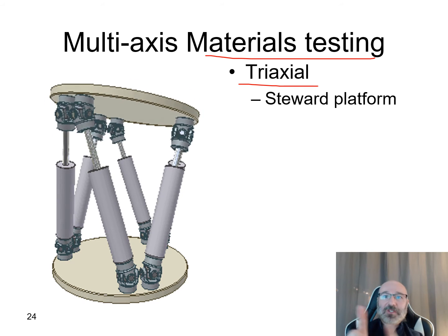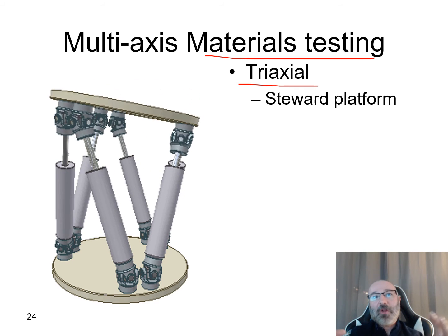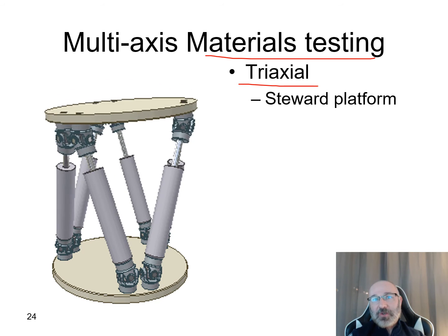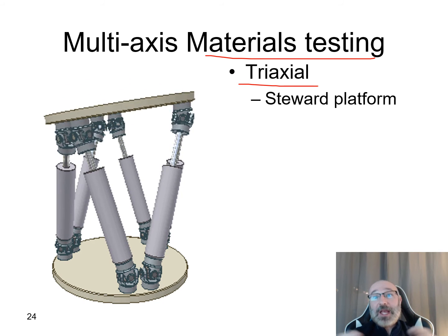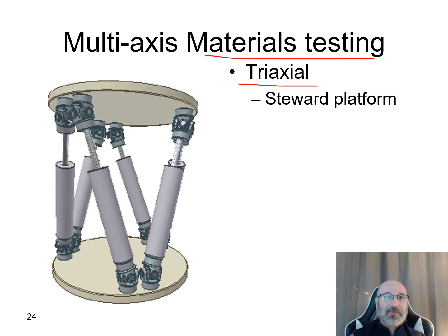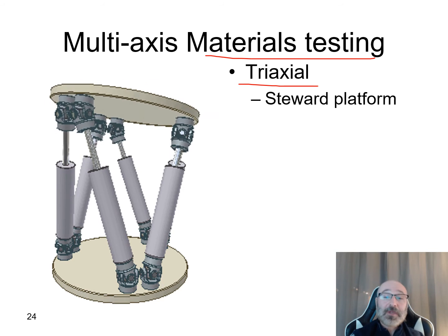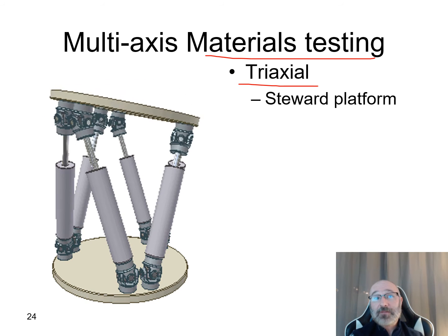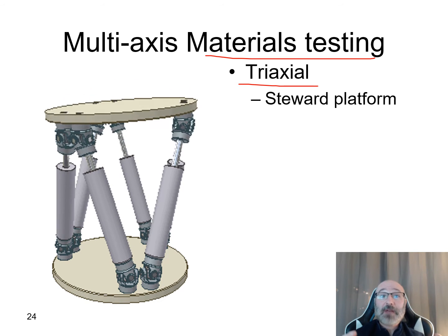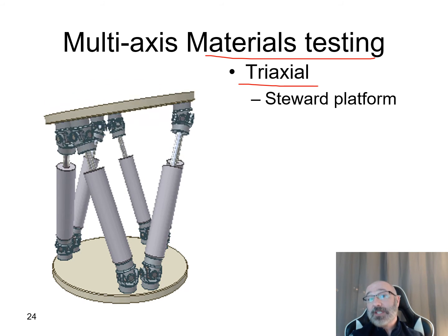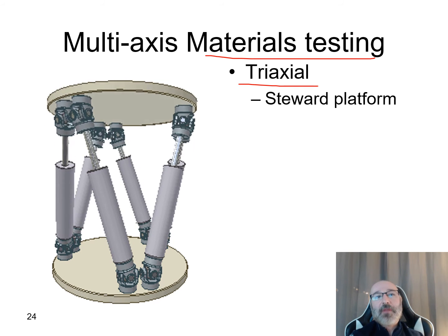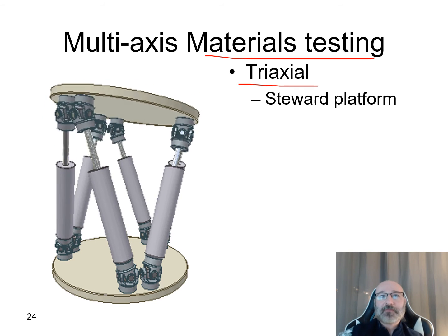A uniaxial machine was just going to push it in one spot. We needed to expand all the way out. So we worked with a couple of these different companies to come up with a special multi-axial testing machine that would expand out in 360 degrees. Again, these are very specific and awesome, custom designed and built. But there are companies out there, even some of the bigger names, that will either custom make one from scratch, or they can have attachments, modifications and add-ons to some of their existing basic tension testing machines or material testing machines that let you expand into multi-dimension.